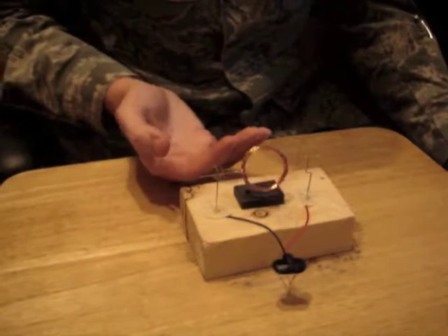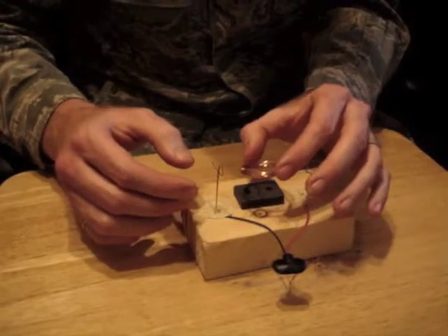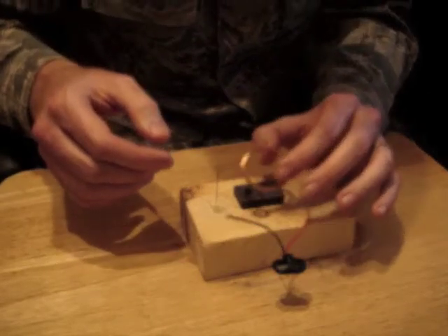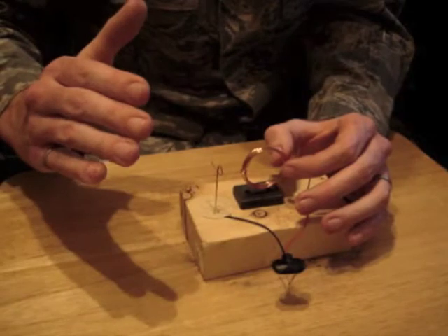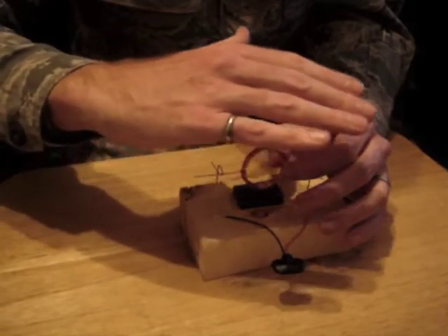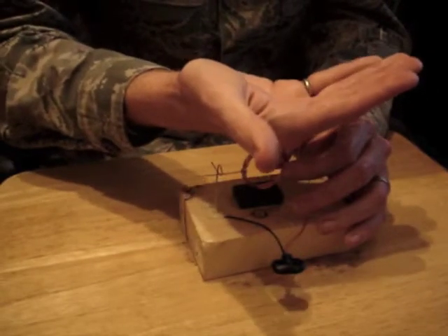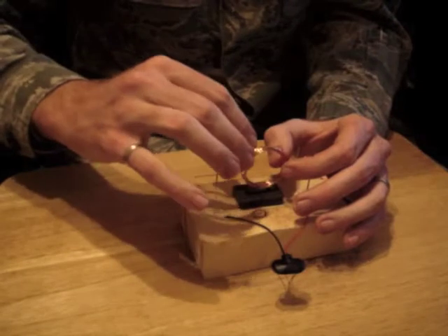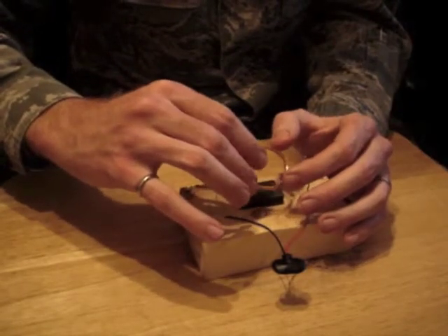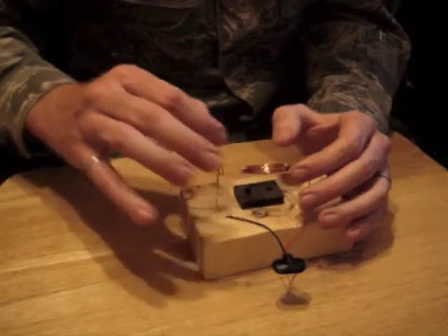The magnetic field is protruding up from the bottom, and using the right-hand rule, the current will be flowing along the top of the wire when connected. The resultant force is going to be this way, causing a clockwise rotation of the rotor.